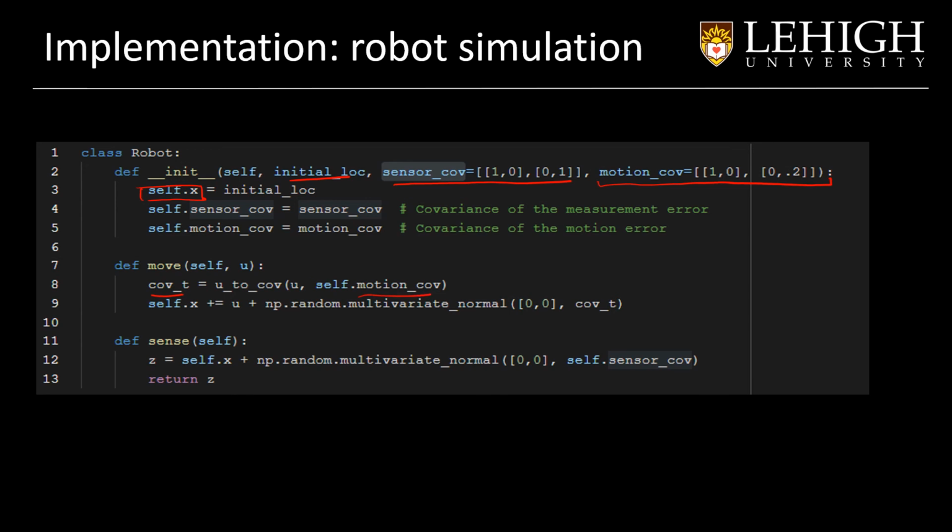Like, if the robot moves here, it will move like this, but if it moves longer, that covariance should grow. So it will be proportional to the distance, and also proportional to the error in X and Y and the direction of the control input.